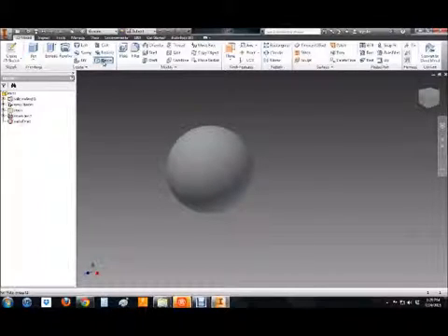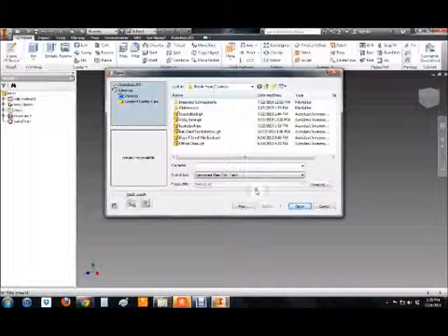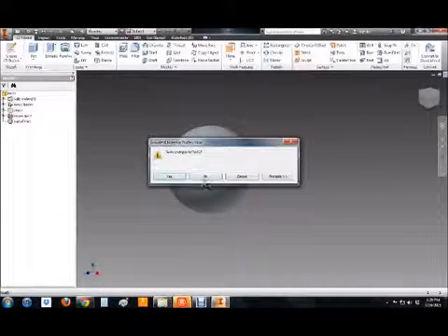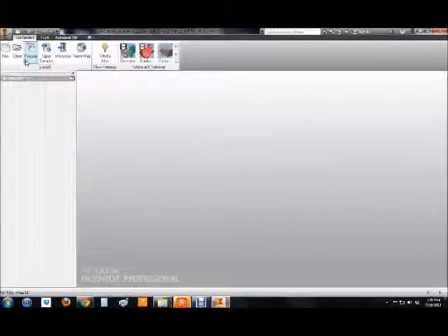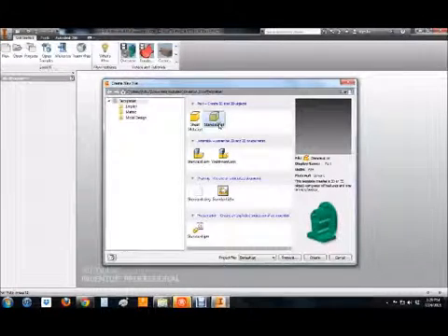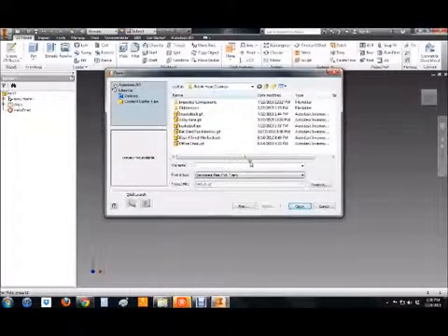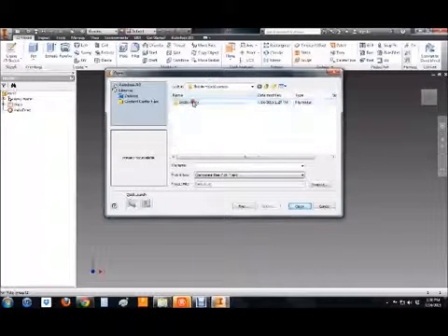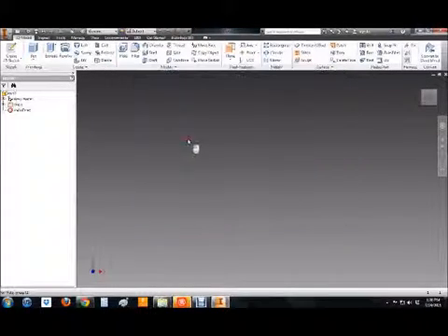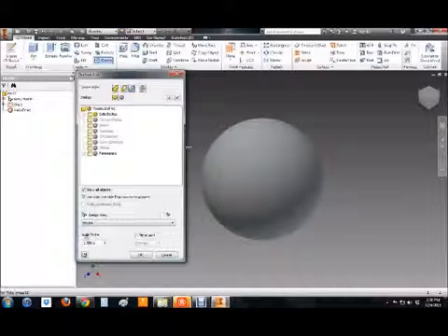But we're going to go to Derive, and we're going to open up. Actually, we have to cancel this. So I have to close this. Save it, no, new, standard IPT, Derive, and it wants to know what to open. So we're going to go, let's see, imported, and it's in here, Basketball 7. And what it wants to do is scale it on the bottom. And so the scaling can be tricky.